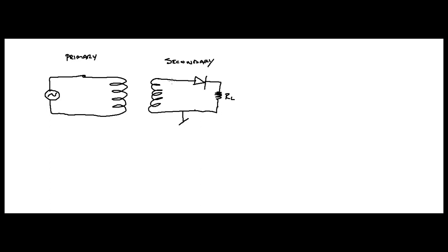If you take a voltmeter, we touch each end here. This right here is your V secondary. It's across each side of this transformer. Likewise, this here is your V primary, all right?